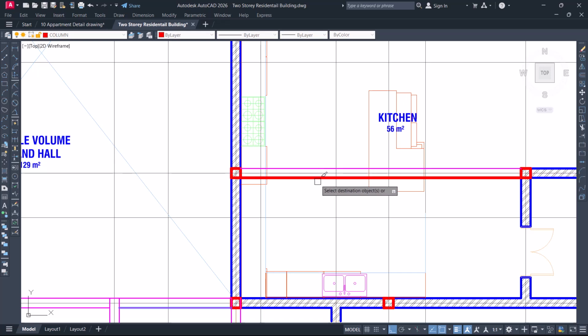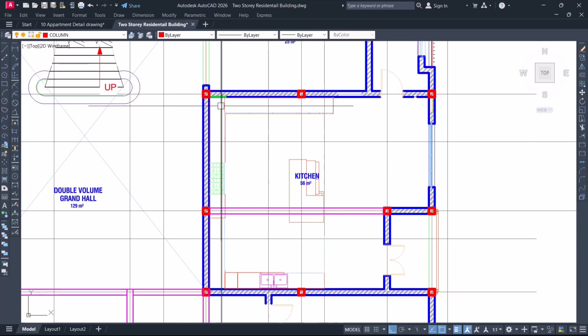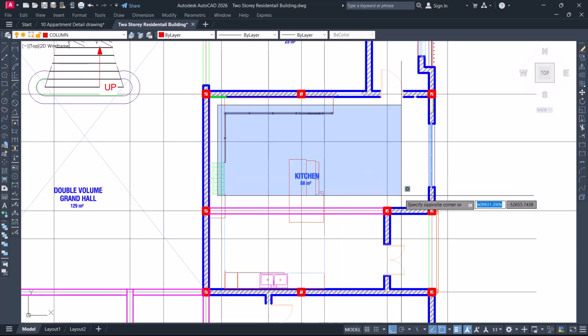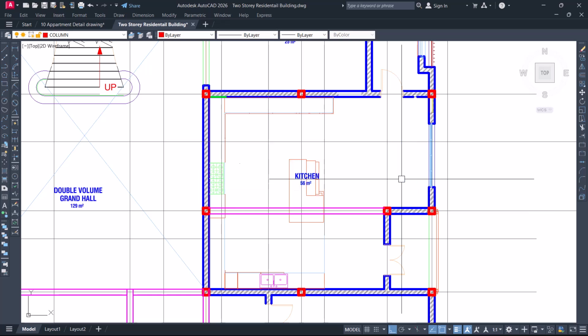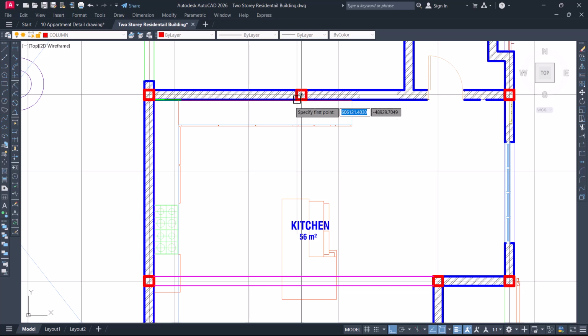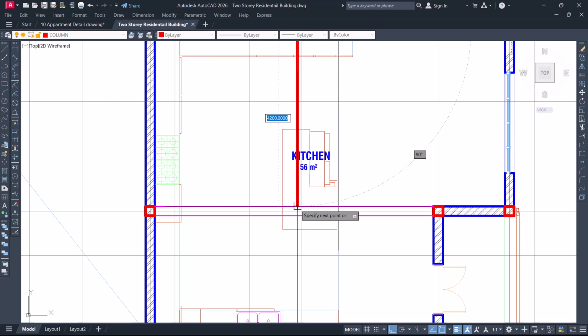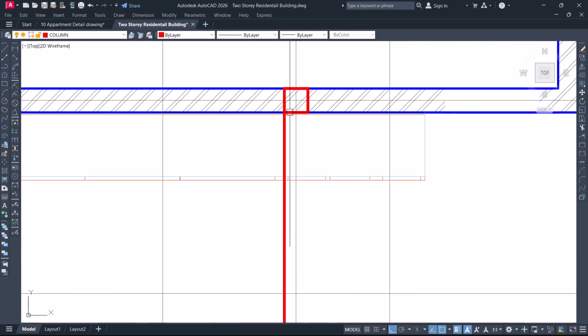After our design, we will know the actual section of the column. Okay, that's fine. Again, now let's see. This panel also seems to be too big, right? It's already more than 30, so we need to break it too. So I'll break it like this, right? Break it like this. So I'll come and break this again, from here. Now you can choose to break your own anyhow you want, but make sure they are structurally framed.